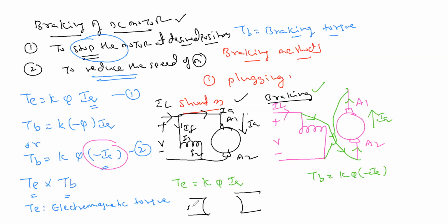Internally, what is happening? North and south. For example, the armature current is into the plane, out of the plane, and then rotation is going. Which direction will it go? It is a motor, so I apply Fleming's left hand rule for torque. Four fingers along the field direction, center finger inside. So the rotation, this is T, the electromagnetic torque direction. Rotation.